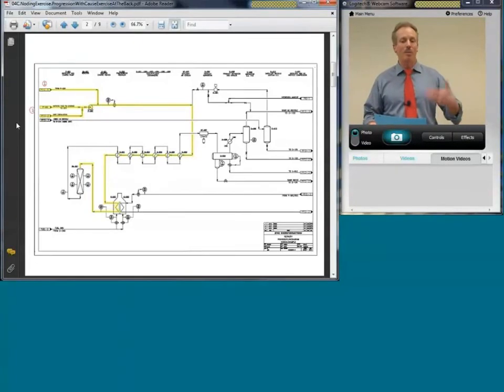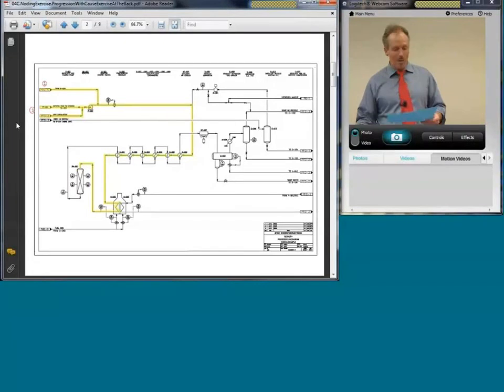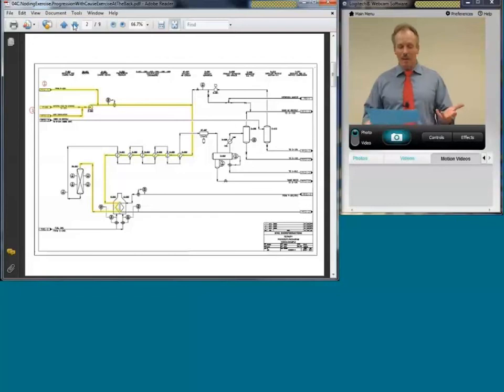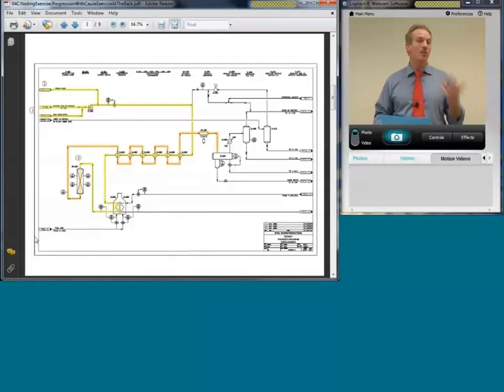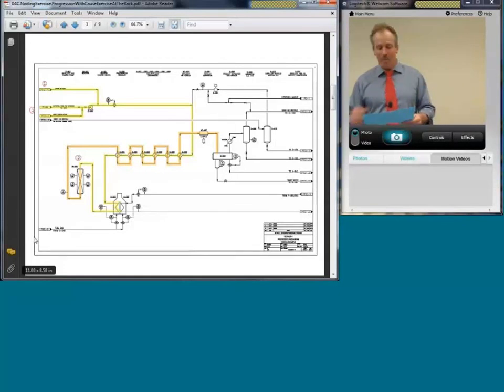That works really well because you get a few active components, and you get very similar impacts on all your heat exchangers as they come in. For the second node, I would follow the process and take the reactor itself and the effluent going back to the heat exchangers that you will have just discussed with the team, and then finally to a fin fan cooler on its way into the product separator.